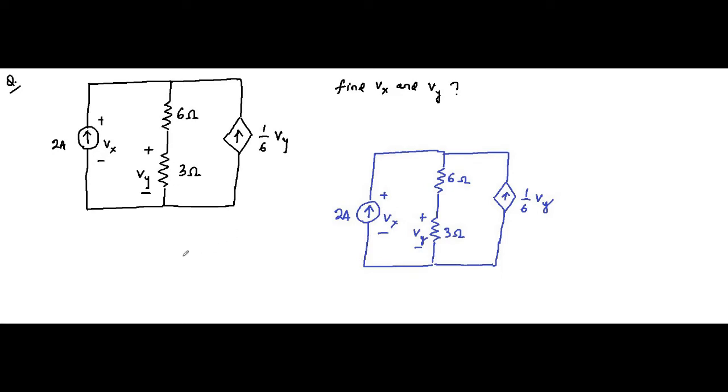Most of the time when it comes to a circuit, we are never asked questions like that, but when you are new to network theory or circuit theory, what we think is that the voltage across a current source, independent or dependent, whatever it is, is 0. Most students getting started with circuit theory think that it is 0.